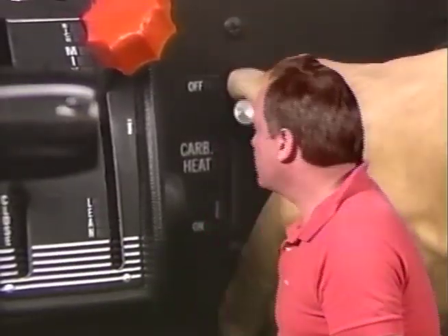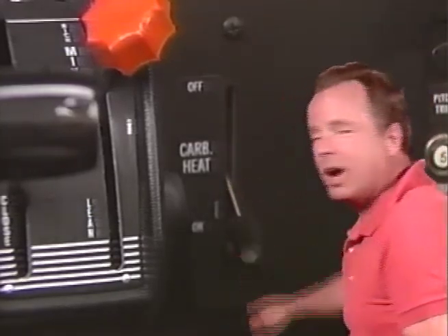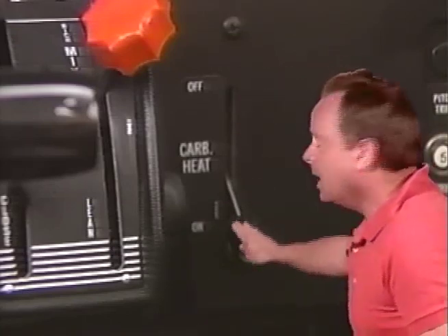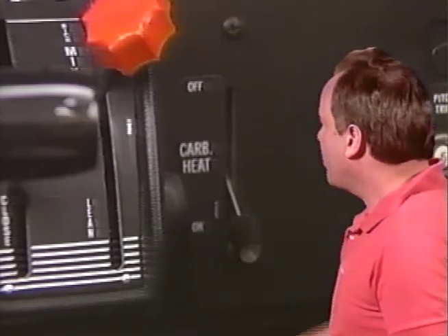Now, when operating an engine, the application of carburetor heat will affect the fuel-air mixture. How? Well, if you apply carburetor heat, as I said earlier, it enriches the mixture until the automatic mixture control on some engines can make a compensation and will decrease the weight of the fuel-air charge. But generally, what you need to know is that when you apply carburetor heat, you enrich the mixture on the engine. Should you use carburetor heat like this when it's not needed? No, the answer is no, you don't want to, because, as we said earlier, you have a decrease in power and possible detonation. So you only use carburetor heat when you think there is an icing situation possible.